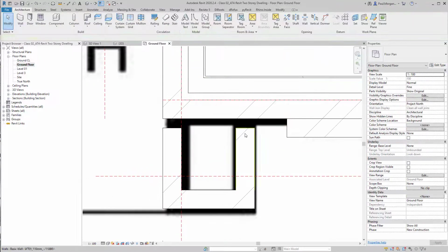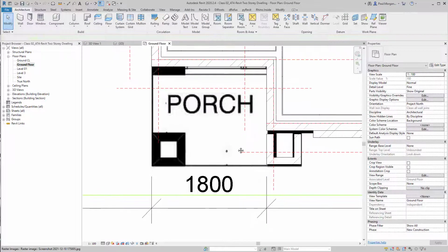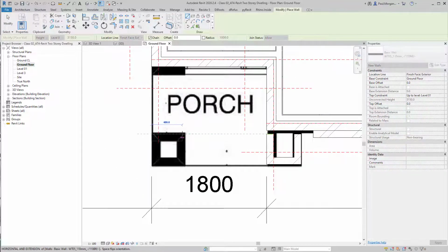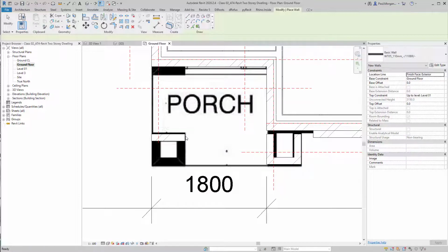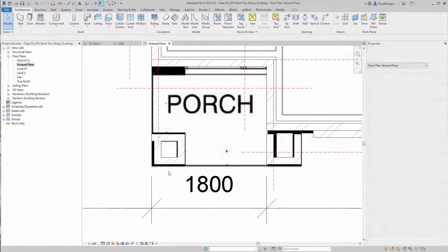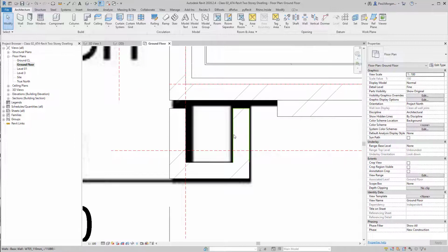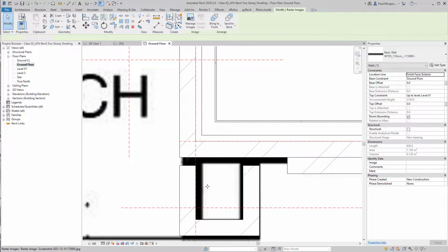And what I'm going to do is I've got this wall here now, and I've got these two walls here, or this U shape. I'm going to quickly draw up this wall as well, just going around clockwise. And you can see at the moment I don't really care what size this is, and I'll just trim that off because we'll dimension that. But just quickly, I want to make sure that I disallow these joins. So I'm going to click on this wall here, and then on the little blue grip, I'm going to right click on that and then say disallow join.